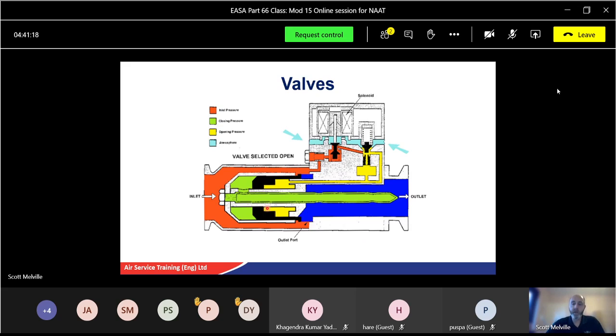In the valves, the air start valves we use are basically simple on-off valves. So you have a solenoid which will energize. Air will always be available from the APU if you select it, but until you energize the solenoid, it won't allow the valve to open. Once it's opened, the gate will open, and the air can then flow through the outside of the valve into the starter itself. So the air valve is dead simple, but again, only about 28, maybe 30 psi coming out of there.